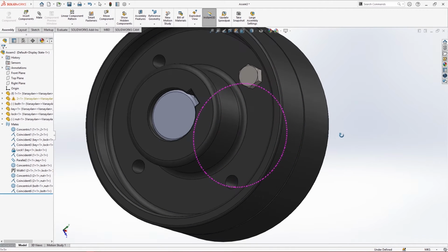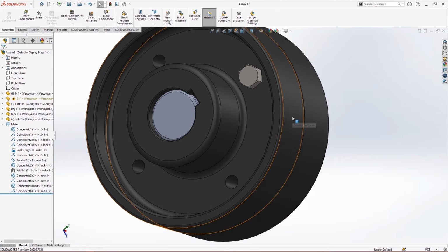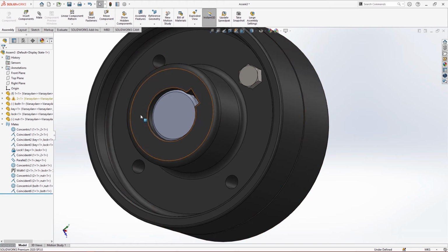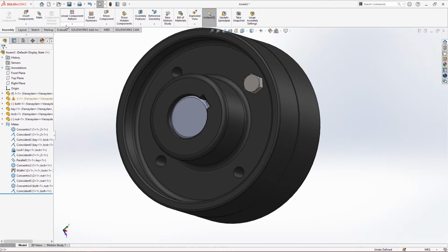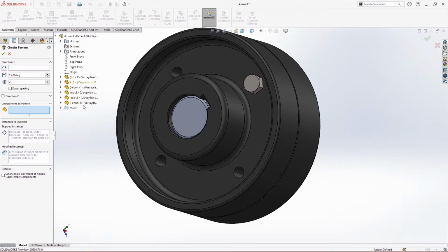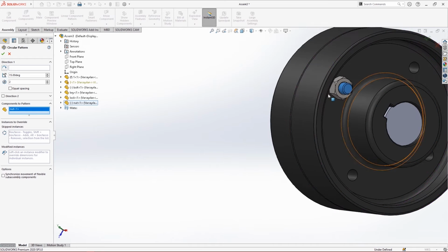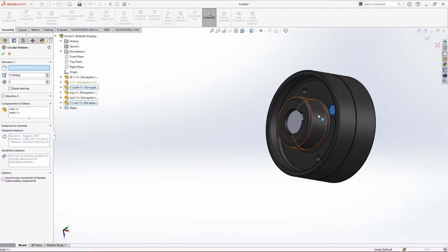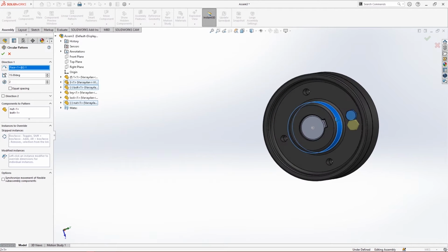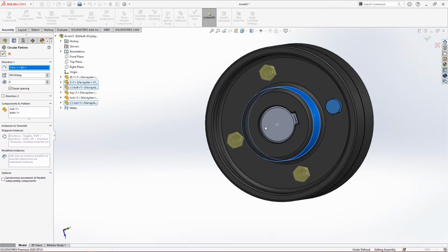Now you can see there are 4 more holes, so you have the option that you can import those files again and apply those screws here. Otherwise, you can just use the linear component, go to circular pattern here, and you can select the component to pattern. I want to apply this nut and this bolt. You can select the direction. I want this direction. Now there are actually 4 quantities. Apply equal spacing, and you can see it has been applied.